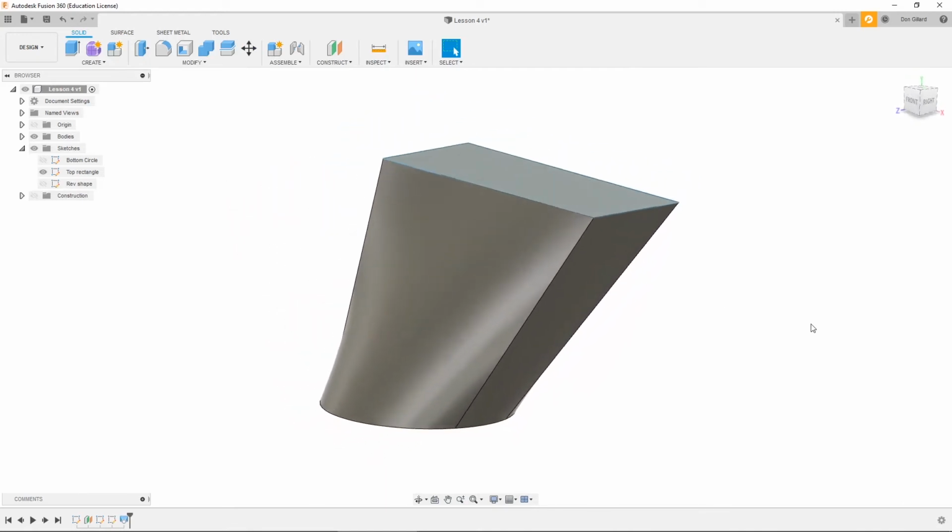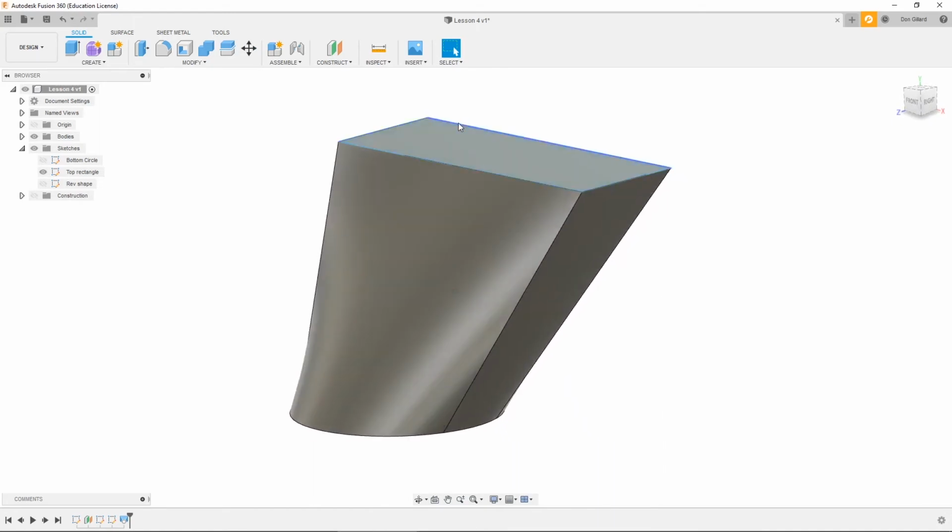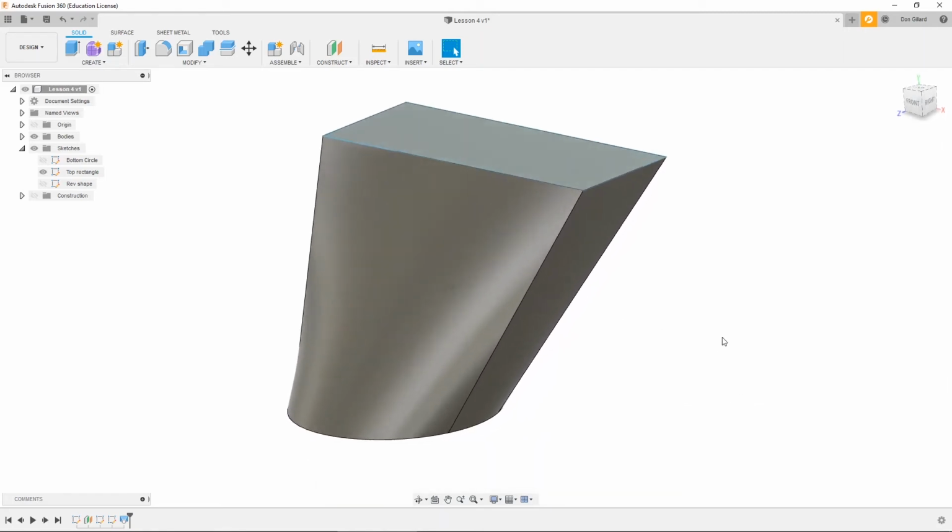Okay, so that's how you loft. And again, it's important you have the matching amount of vertices. So you've got 4 vertices. So you can see they're joining here. It gets a little tricky when you're designing it if it's complex, but you need the same amount of vertices.